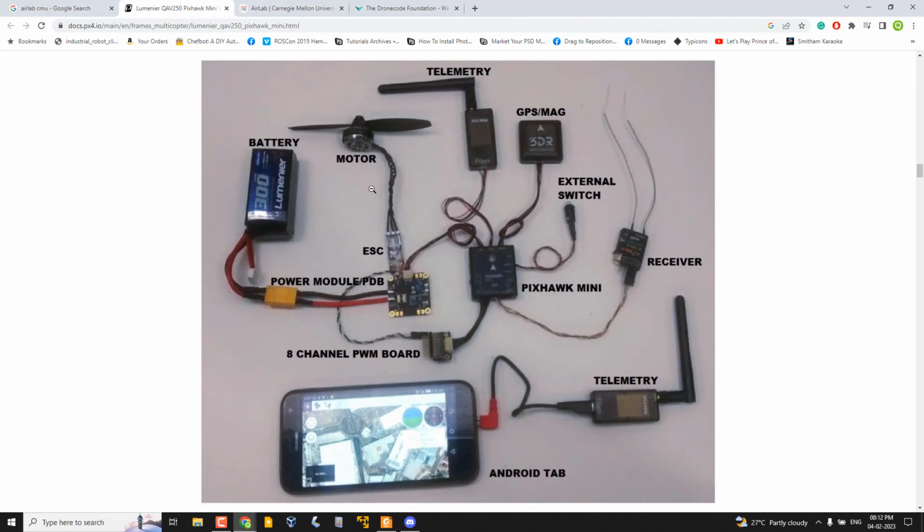Okay, you can see here there are motors. Currently only one motor is connected, and in order to drive the motor of the drone, yesterday we have discussed, we need an ESC, electronic speed controller. Okay, it's a circuit like the motor controller. So the ESC regulates the speed of the motors. Okay, there are 4 motors. So obviously you may have 4 ESCs, or a single ESC that can drive all the 4 motors.